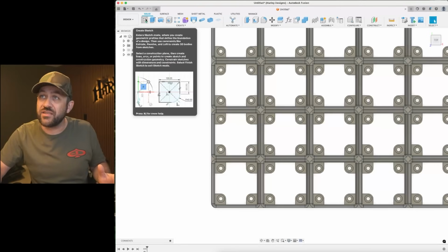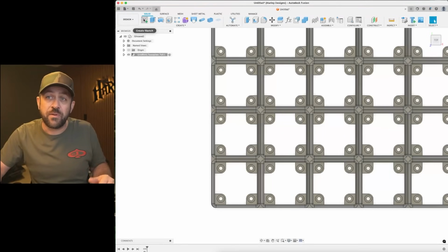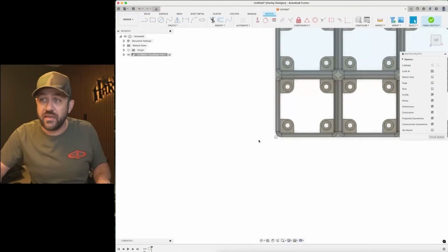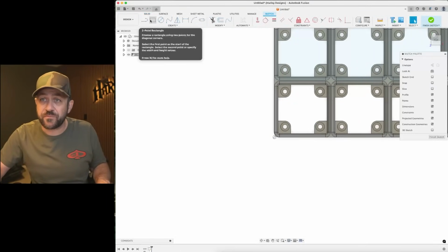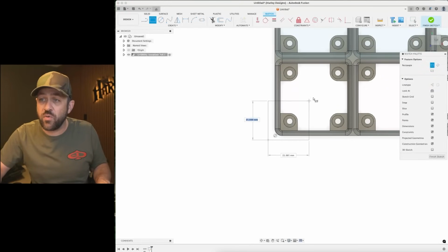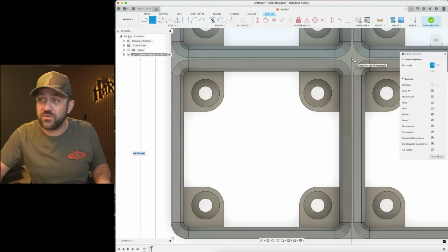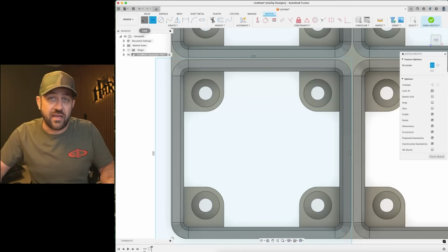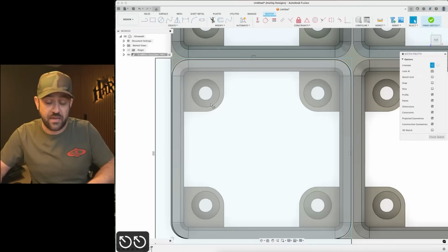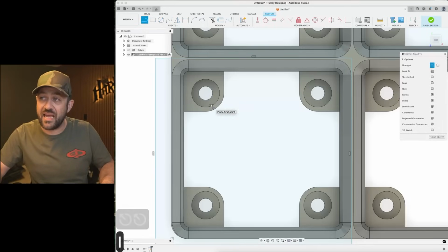And if you wanted to do that, just for a quick example, you come up here to the very top and hit new sketch, come down here, and just to make it simple, you could just select this top surface. And then from there, you just need to make a sketch. So a number of different ways to do that. Let's just do a quick rectangle that's kind of down and dirty between everything. You could add a line by clicking up here. You can come over here and toggle to construction, or you could do that same thing by clicking L on your keyboard and then X to toggle construction on or off.